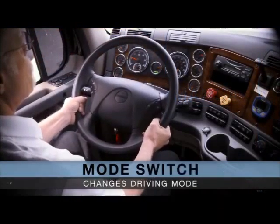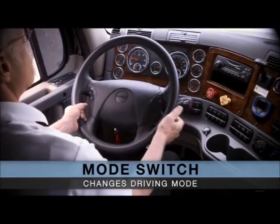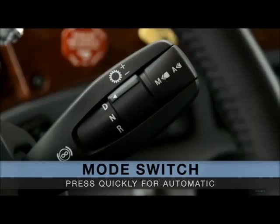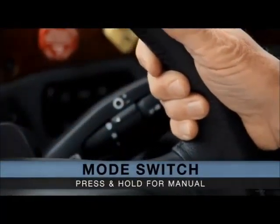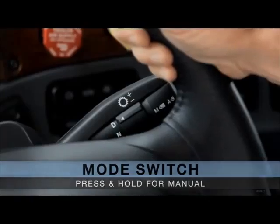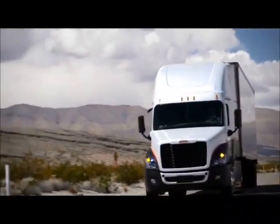The driving mode can be changed using the mode switch located on the end of the shift control. Press the switch quickly to activate the automatic drive mode or change between automatic economy and automatic performance modes. To activate the manual drive mode, press and hold the switch for about 1 second. In any driving mode, gear shifts can be requested manually.